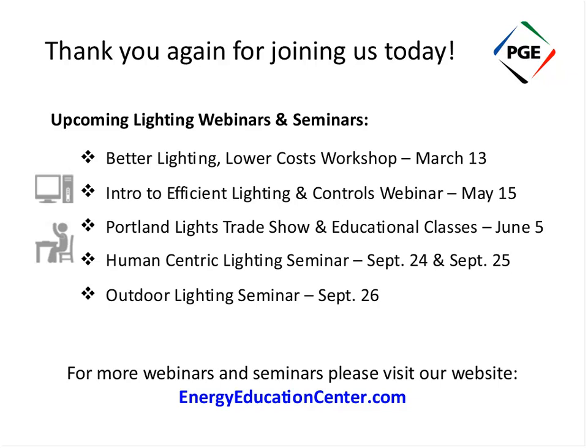LEDs, because they start out as a blue light, have to be converted to a warmer source. And one of the challenges with having LEDs be warm is that the efficacy, the lumens per watt, goes down the warmer the LED gets. At least that's the case at the moment.